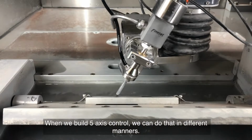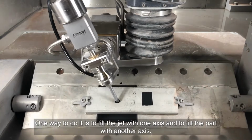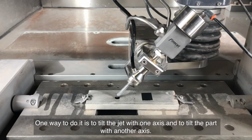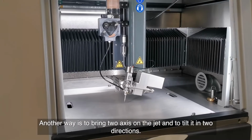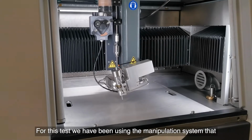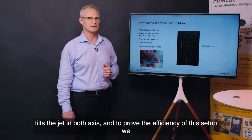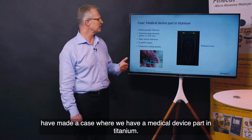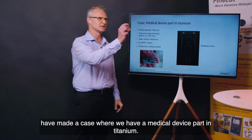When we build 5-axis control, we can do that in different manners. One way to do it is to tilt the jet with one axis and to tilt the part with another axis. Another way is to bring 2 axes on the jet and to tilt it in 2 directions. For this test we have been using the manipulation system that tilts the jet in both axes, and to prove the efficiency of this setup, we have made a case where we have a medical device part in titanium.